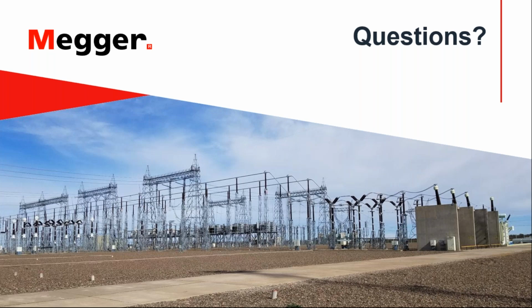What I also want to mention is that if you are thinking about medium voltage GIS, where you have other breakers that you don't have access to, DRM won't work there either. You just need to detect the voltage coming or disappearing or showing up.